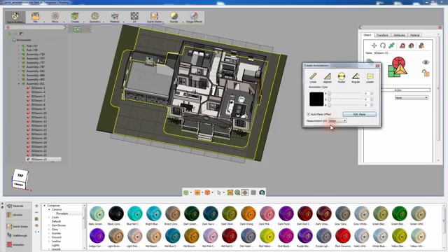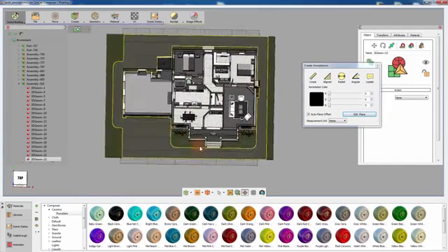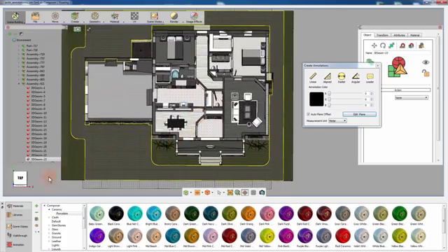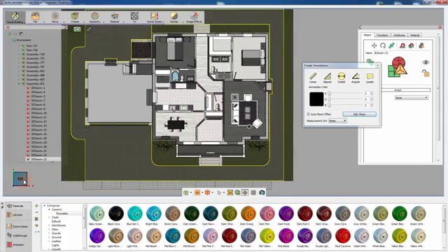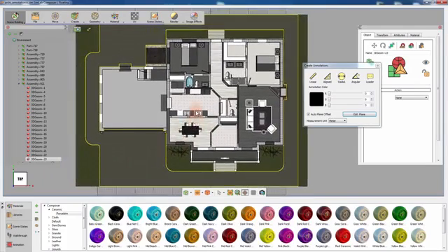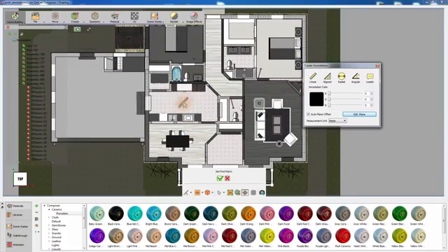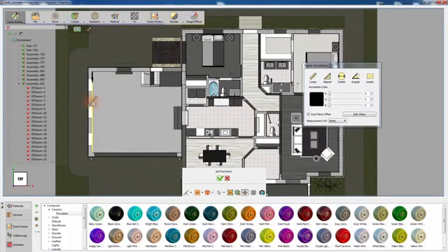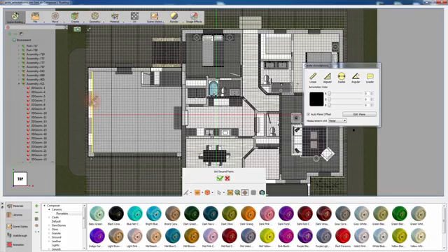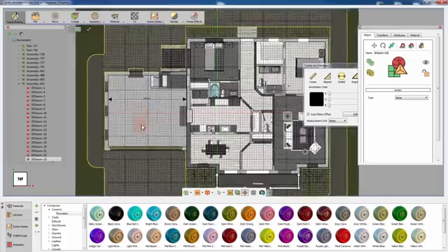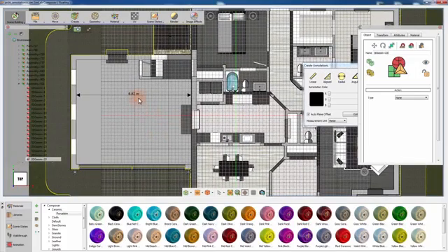Click OK to confirm the plane and go back to the Annotations dialog. Following the same steps as earlier, create a linear dimension. Then set the 2 points of measurement by clicking on edges. Then set the position of the measurement text and left-click in the position to confirm the creation.